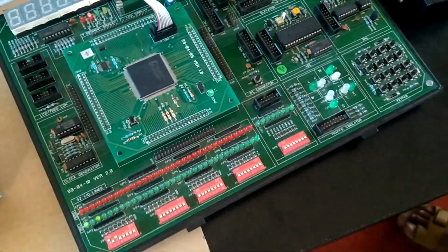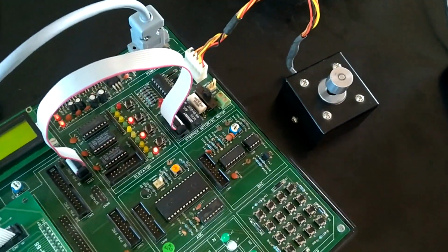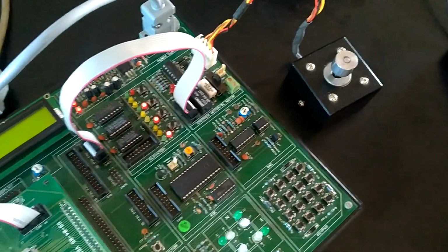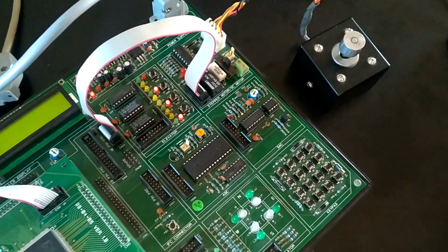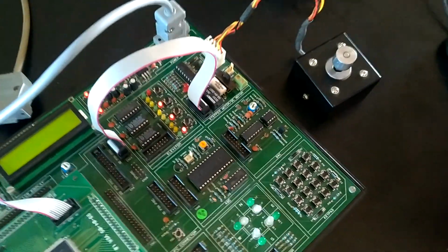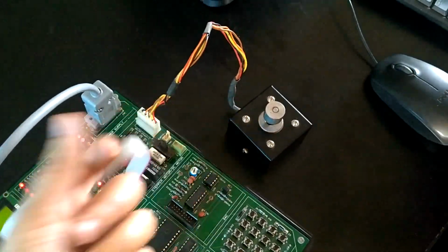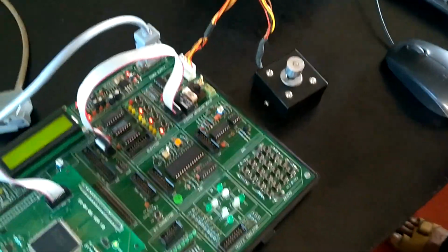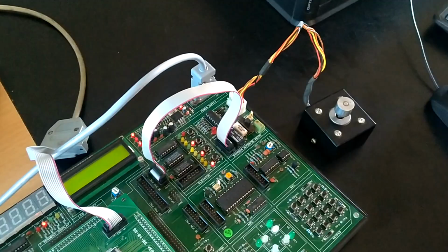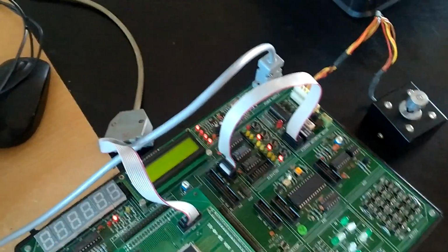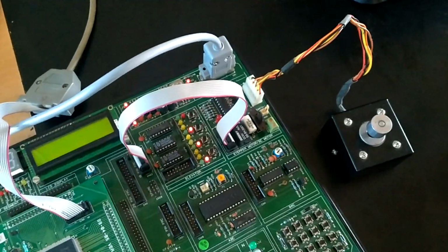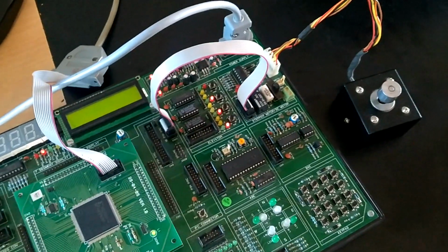You can even set the stepper motor directions, like you can reduce the step or you can increase the speed also, but it is not necessary to increase the speed and etc. here, because we need to know the steps here. But we can stop this particular stepper motor at 90 degree or whatever the degree we want. For each single step it is around 1.8 degree of step rotation is needed. So based on that we can calculate it. Okay, thank you.